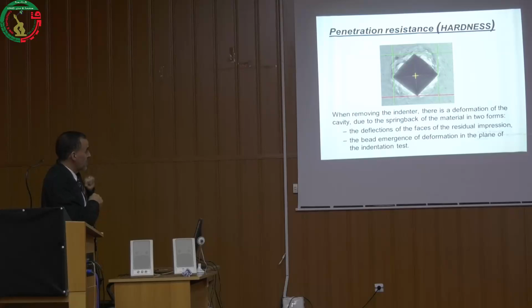When removing the indenter, we can see there is a deformation of the cavity on the edges due to spring back of the material in two forms: deflections of the faces of the residual impression and the bead emergence of deformation in the plane of the indentation test. This can lead to imprecision in the results.